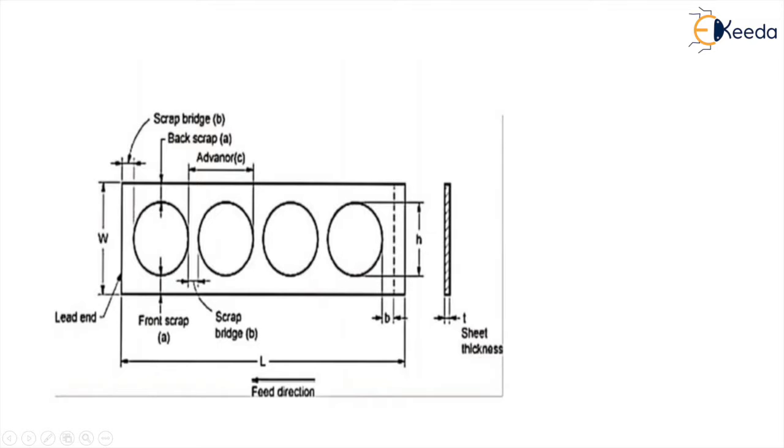Okay, and this total blank size plus the scrap bridge, this total distance is our advance, or we can also call it the feed. So if the diameter of the blank is D, then D plus this small a is our feed. We can say it as S, or here we have noted it as advance C.